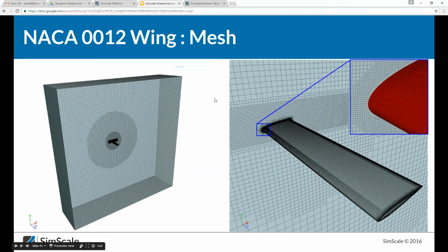Okay, a zoom in of the layer mesh. You can see in this case we have taken only 2 layers. This is because we want to keep the mesh sizes low for such a sample project, but for real analysis, or if you want a very good validation, it is recommended to have at least 5. Close to 7 would be appropriate.